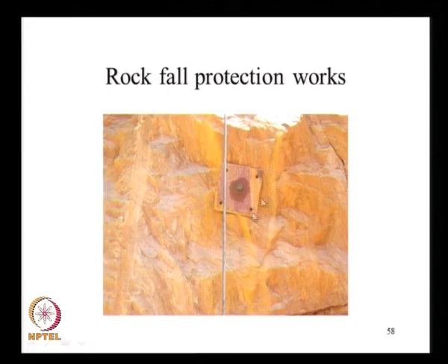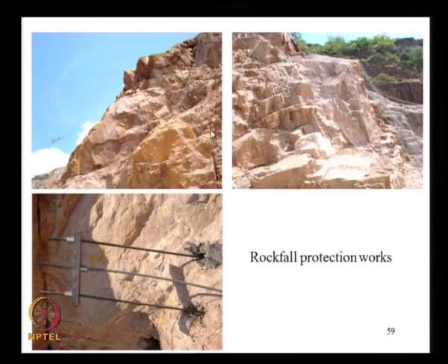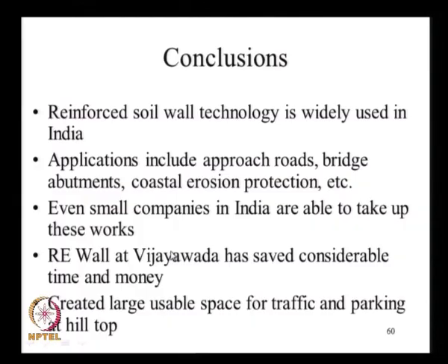And along with this construction, a number of rockfall protection measures had to be taken. Here you can see an anchor that was installed and that was bolted down to stabilize the rocks, and some rock netting was given along with nails.